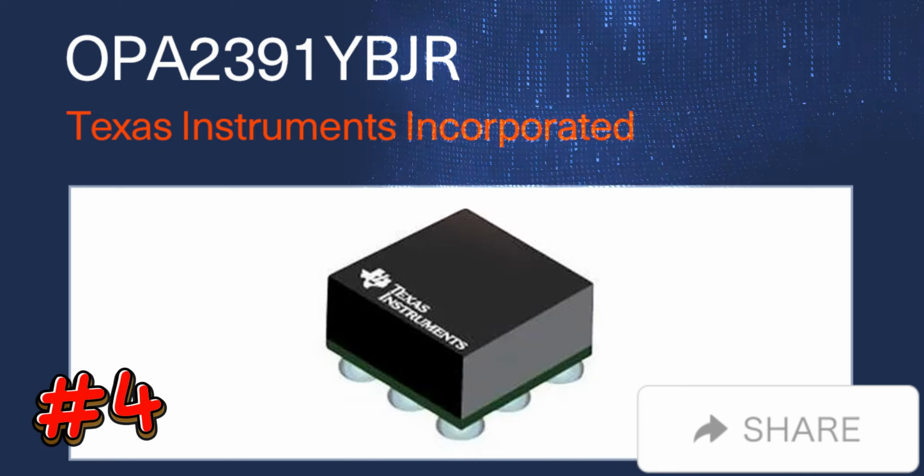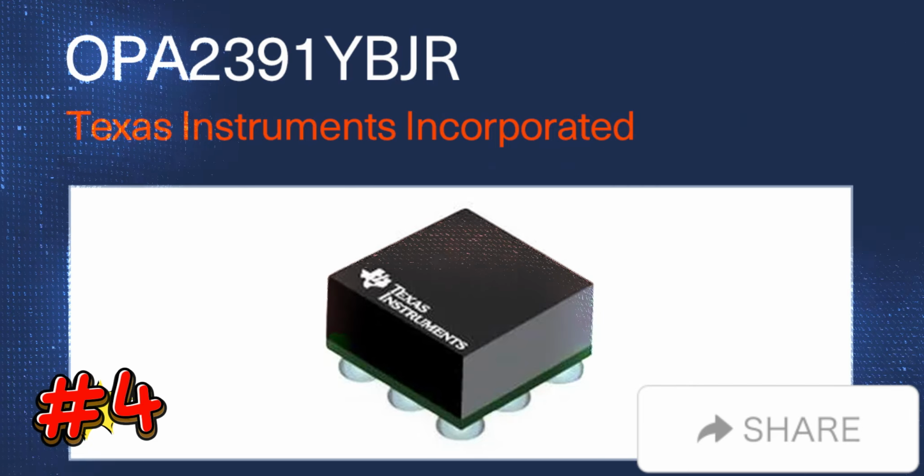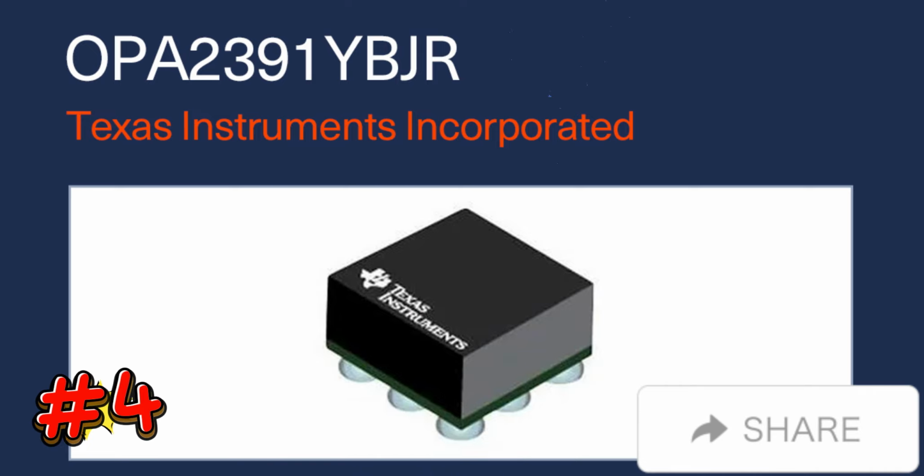Fourth on the list is the Texas Instruments Incorporated OPA2391YBJR. The dual micro-power precision op-amp with the DSBGA package, the OPA2391YBJR features a unique combination of high bandwidth, 1 MHz, and very low quiescent current, 24 microamps.